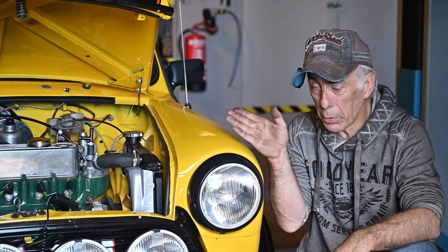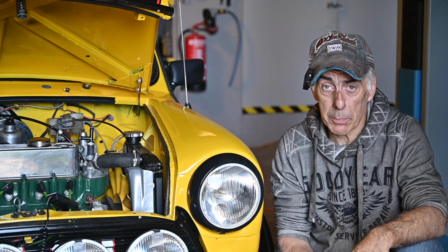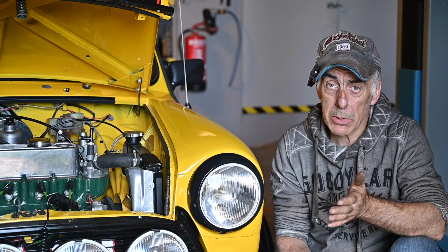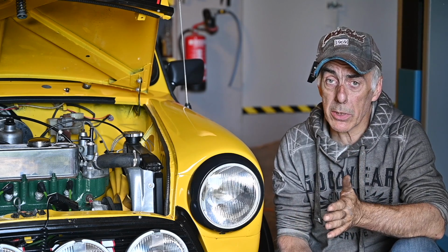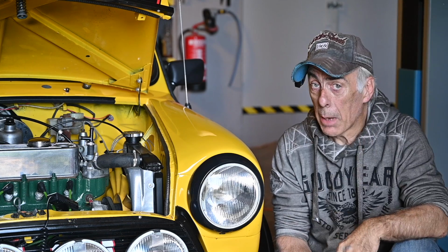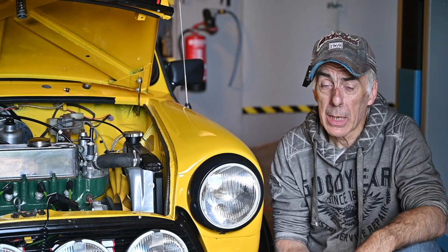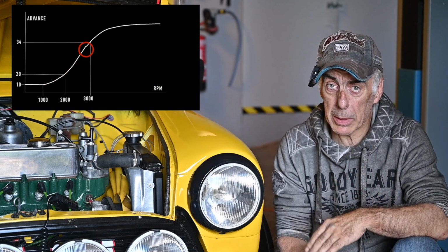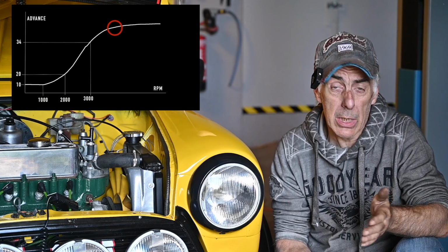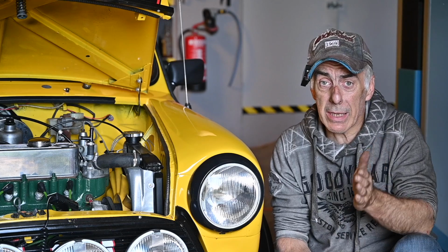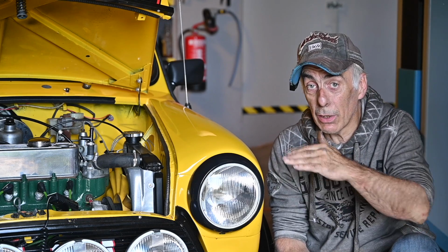And the way that is done is you use your strobe light, you look at your pulley, and then you increase the RPMs. So have someone push the throttle or whatever to a certain amount of RPMs. You need to know what the RPMs are, and then you can actually see where the marker is on the pulley and how many degrees advance you have. And you can do this in multiple steps, 1,000, 2,000, 3,000, 4,000 RPM, the way you like to do it, and you can actually plot it so you can create your own curve. It's a bit difficult if the advance is going off the scale of your pointers.